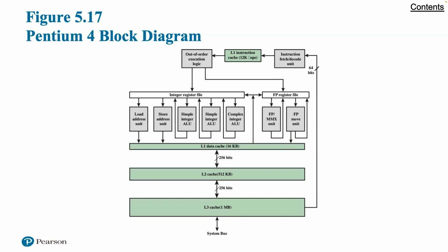As discussed more thoroughly in Chapter 18, the Pentium processor decodes, or translates, Pentium machine instructions into simple RISC-like instructions (reduced instruction set computing instructions) called micro-operations. The use of simple fixed-length micro-operations enables the use of superscalar pipeline and scheduling techniques that enhance performance.